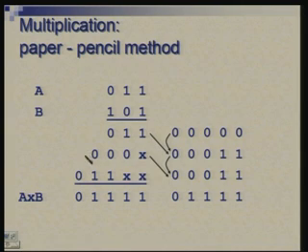You would notice that at any time one of the values which you are adding is only n bit. It is only when you look at the whole thing that it is 2 n bit wide, but if you look at each addition you are adding one n bit value in some position. So, if you focus on that, you need to have only an n bit adder. There is nothing changing on the right of it, there is nothing changing on the left of it. So, if you arrange your information such that you are taking care of those n bits where the new value is positioned, you can work with an n bit adder.